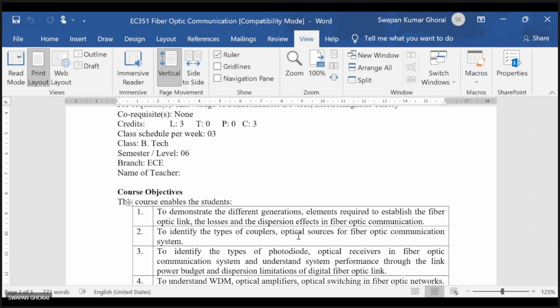This is most important because the transmitter is based on optical sources. Say what I'm talking, these voice signals, speech signals, cannot be directly transmitted through optical fiber. You have to convert them into current first. Next, it will be used to modulate the optical source. And in the optical fiber, the signal that propagates is the optical signal, not the electrical signal.